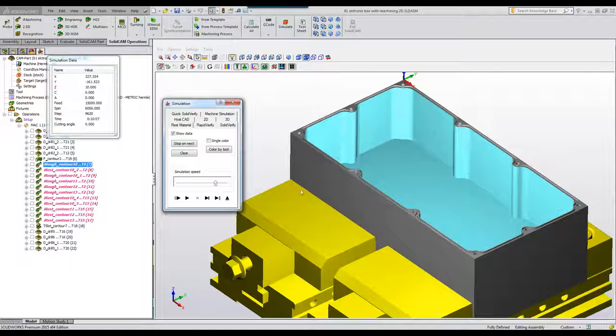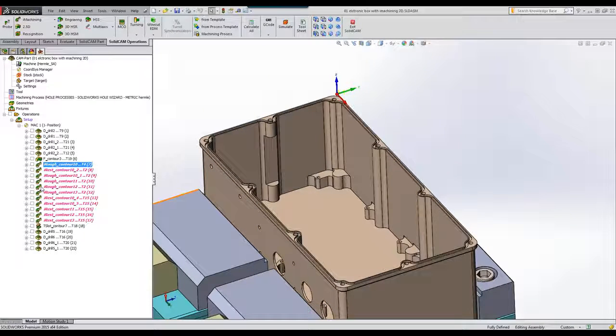Okay? Now, in my next particular operation, I decided already to start off with my rest rough for that particular geometry, since I was already in that geometry. So I did a rest roughing operation just to finish out those corners. But then I wanted to go down to the actual step down over there.